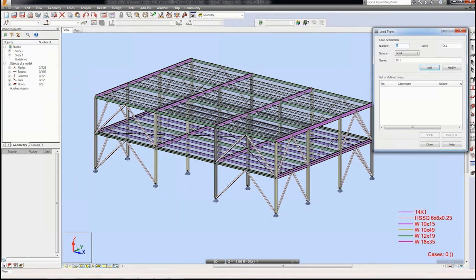Okay, we can then start looking at adding our load types. So you'll see here we can set up a title for the name and add it in. So it's a live load, dead load, wind, snow load, for example, and you can set up the actual information within there. Okay, so you go through and give it its name appropriately on the screen. Okay, and once we've done that, obviously we can take it one step further and actually start applying the loads within here.